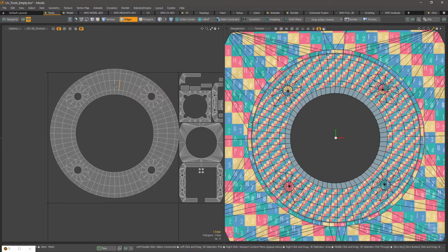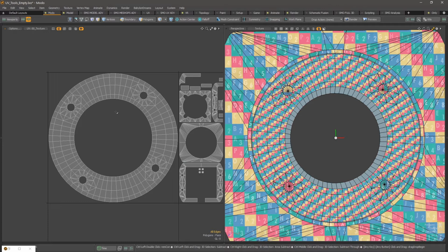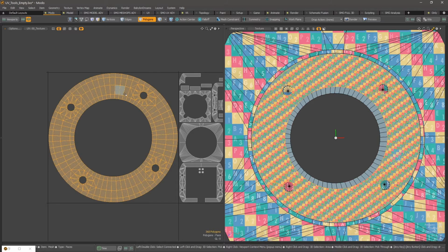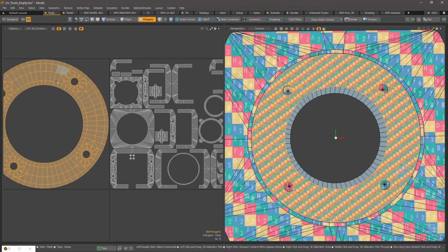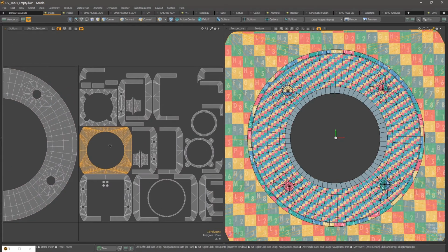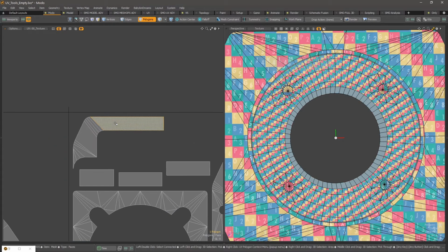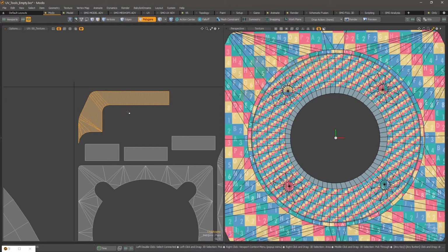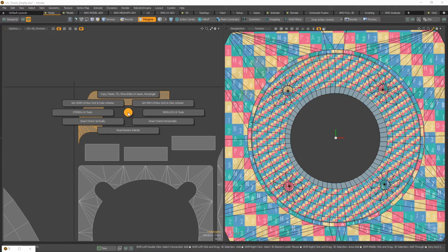But if you want to do this in polygon mode, you can go back. So I will go back here. Here we have the selection. Of course, this one is just a round circle, so it will not be visible at all. I will do this over here, and we'll press Ctrl Q, and I will set this horizontally.